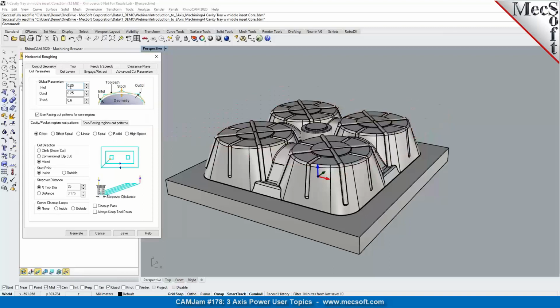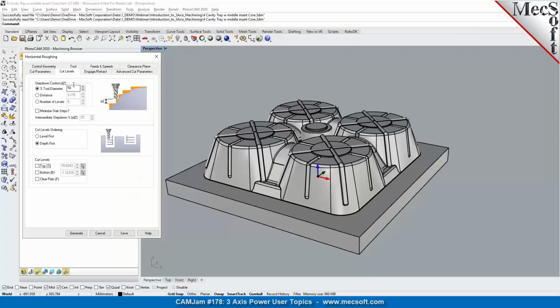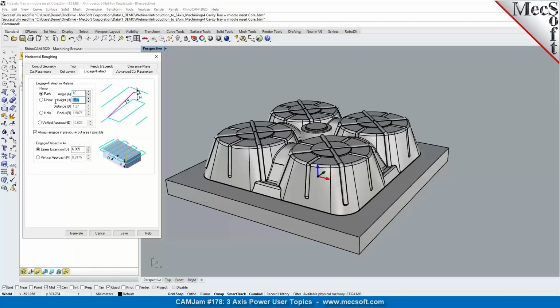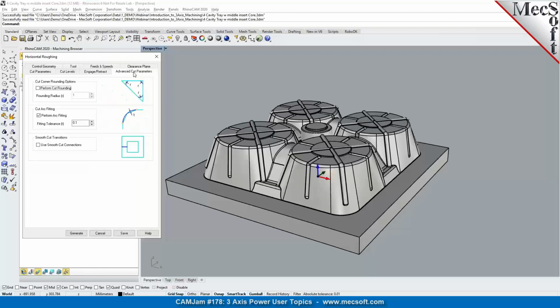And cutting parameters, like I could set my tolerances to be a certain setting at all times, and the stock to leave. So each of these parameters that you're inputting, you're basically repeating this over and over again for each and every time you're trying to generate any operation. All of the mop parameters that you're specifying in here have to be keyed in or inputted each time. So this repetitive work can be eliminated by defining or setting up defaults.